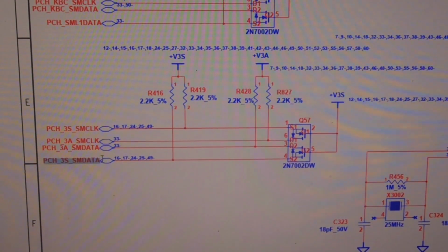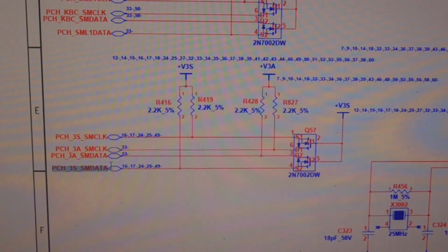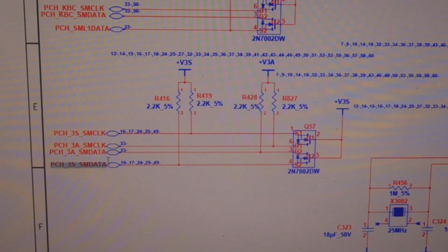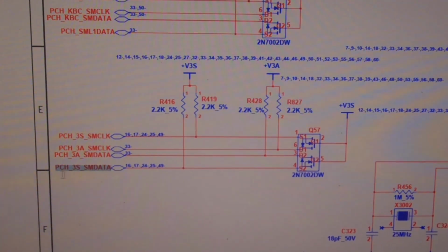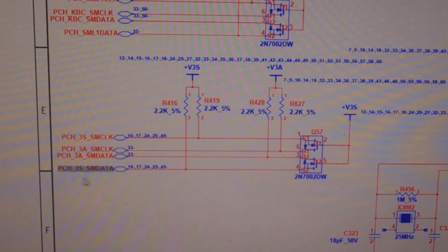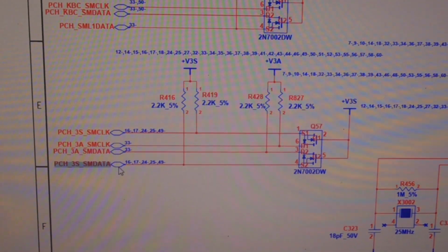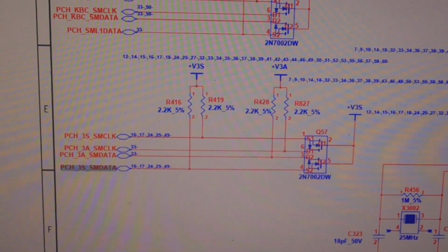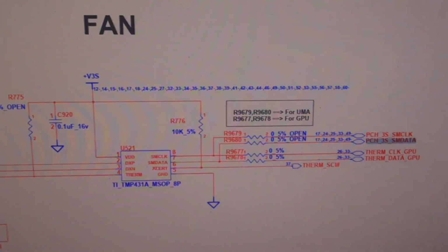Some components inside the PCH would have been damaged, and that is making the voltage for this system data line drop from 3.3 volt back to 1.4 volt. So let's isolate the areas one by one wherever it goes and look for a solution. Let's hope for the best.